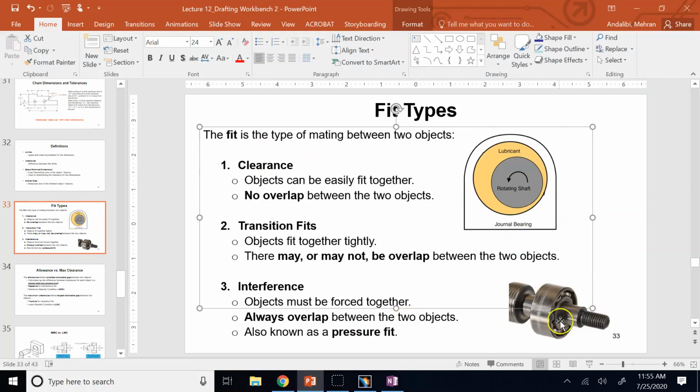So the shaft rotates too fast, and the load applied to the shaft, which will apply to the bearing, is really high, and it changes so badly versus time, that if you want to use these ball bearings, the ball bearing would wear out and it's going to jam, because all of these moving elements inside it, like these balls, will be deformed, okay, because of all that load. They will be deformed, and soon your bearing would jam and the shaft stops rotating. Again, because of too fast a motion and too large a load.